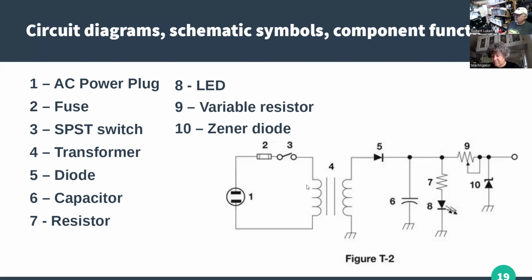If you had the same number of turns on each winding, then the voltage you see on the output would be the same as the input. If you had more turns on the secondary, then you'll see a higher voltage on the output than you saw on the primary. But because there's no power increase, if you had a higher voltage, you're going to have less current, because it would have to be the same power or less as what came in.